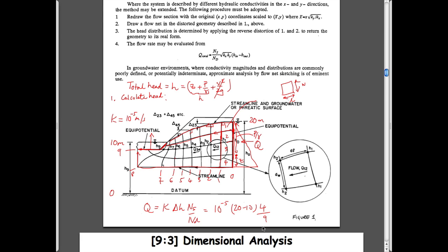So basically, our reasons for looking at streamlines, they're used in a variety of different ways. This is just one application of streamlines: if you can draw something that satisfies the boundary conditions, this is an equipotential, this is an equipotential, and is joined by some streamlines with equipotentials that are 90 degrees to it, if you can just hatch that out yourself, de facto, it represents a true solution to your problem.